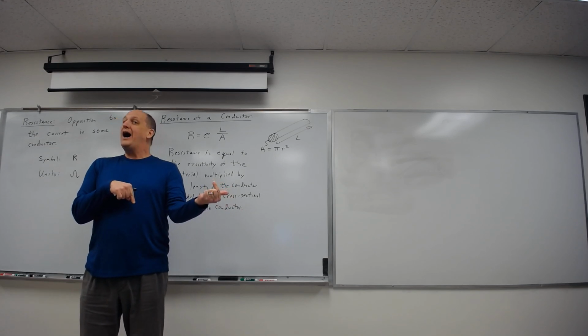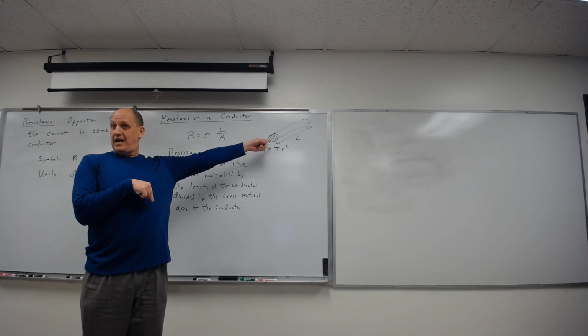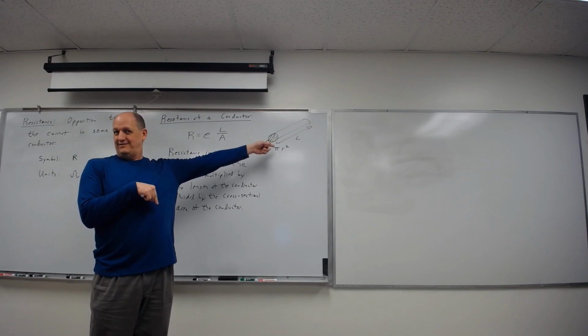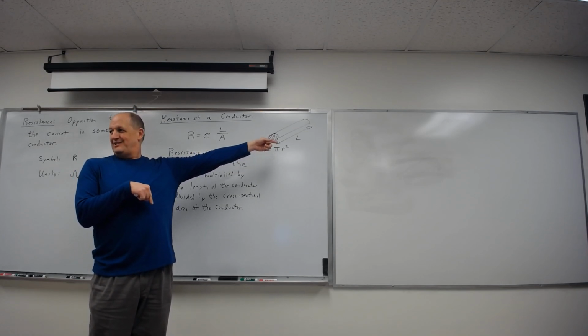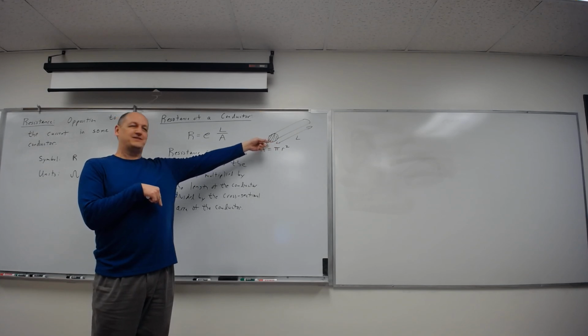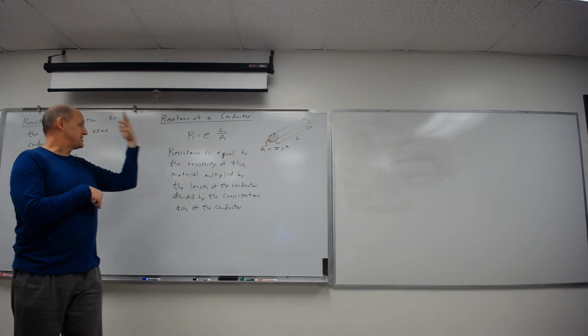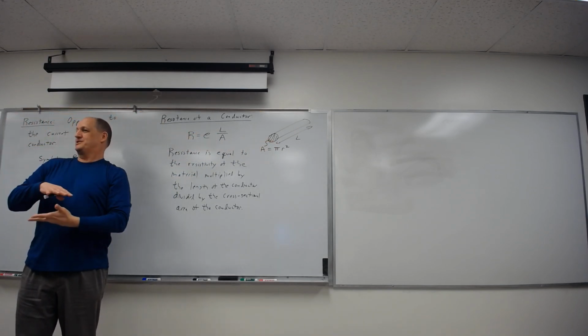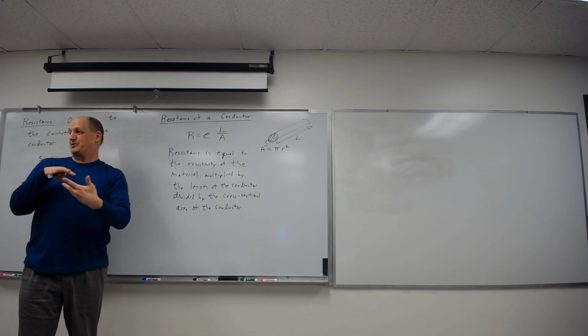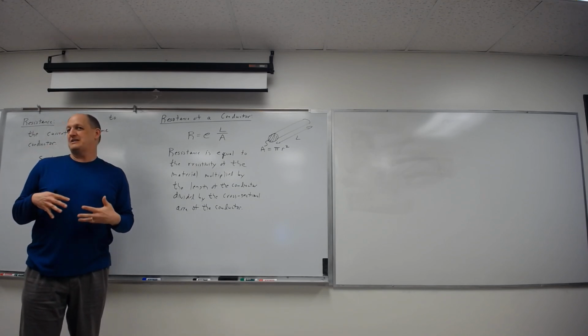That's brownout. Why? Oh, I ran this cable 1,000 feet and it's designed to be usually assumed more like 100 feet. And all of a sudden, because it has enough resistance to the current, by the time it gets to the end, the voltage has dropped. So I don't have nearly as much voltage or current to power everything. That'd be a brownout condition.